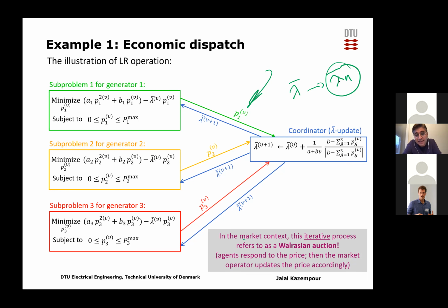No, because as long as you add the transmission system with a linear objective function, it doesn't converge. But as long as you eliminate the transmission system, then all the remaining participants' problems have a quadratic objective function, and then it converges. Sure, but you could make the transmission system problem quadratic by introducing a small quadratic component, though that could be numerically difficult to solve, I guess.